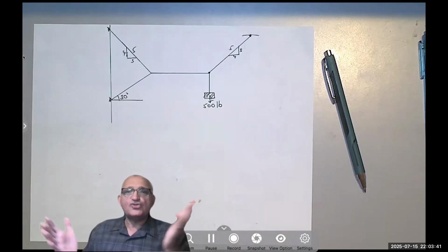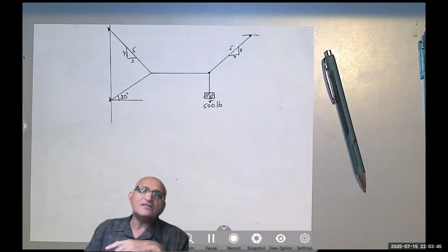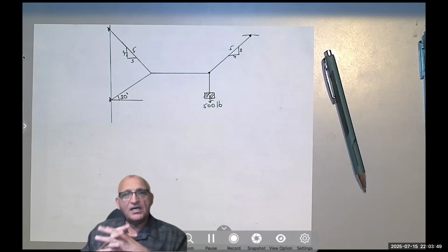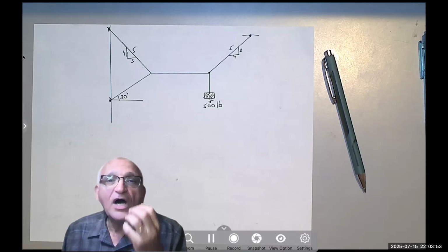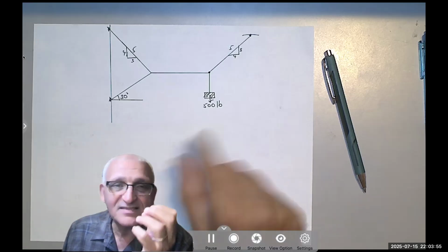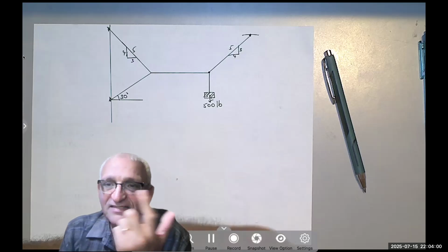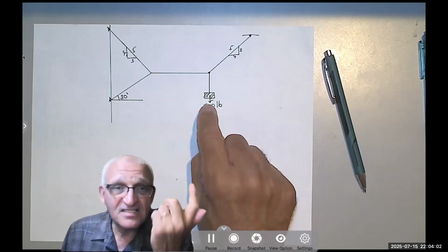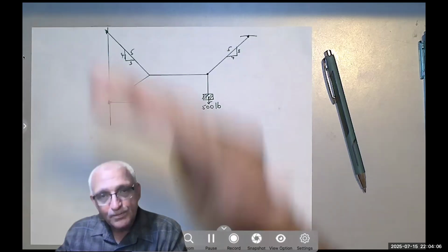Pound is already a force. You don't multiply it by anything. I've seen people multiplying it by 9.8, others multiplying it by 32, because that's the customary Earth acceleration. If you are given the mass, and the mass in the customary system is in slug, if I tell you this is 10 slug or 15 slug, you multiply it by 32 to make it pounds.